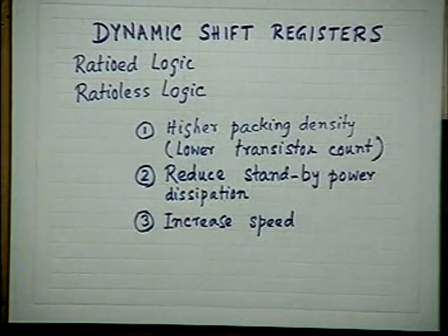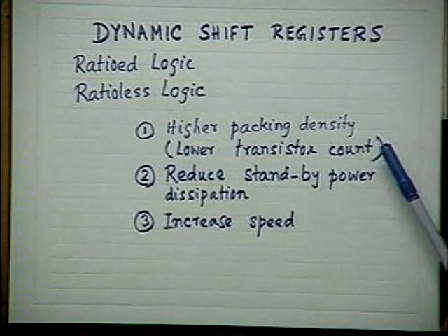Anyway, whenever we consider any digital logic, these are of primary interest to us. One is higher packing density from the VLSI point of view. Second, lower standby power. You know that for single channel cases, the power dissipation is maximum during standby, which I'll discuss afterward. So we want minimum standby power dissipation.